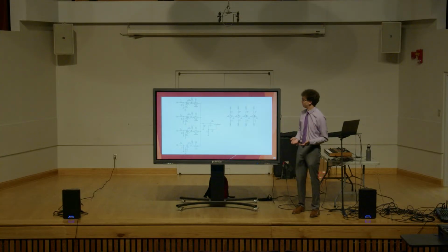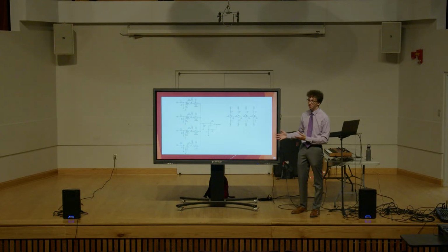And so this is not something that I've breadboarded yet. For now, I'm just using a non-inverting summing amplifier that's a fixed state, and that's good enough for me for now, but I'd intend to implement several OTAs, since those give me voltage controllable volume levels that are then sent through voltage controllable switches, the CD4066s, that are then buffered and amplified through this non-inverting summing amplifier. And so it should just be a relatively simple circuit. I don't imagine that it'll be anything terribly crazy.